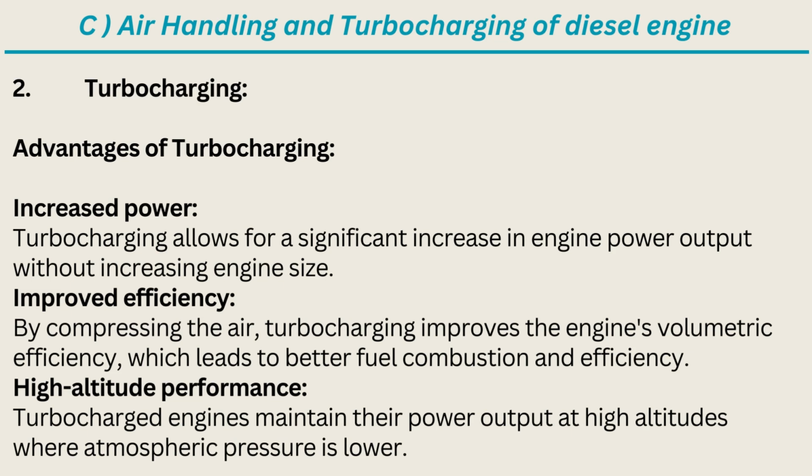Increased power. Turbocharging allows for a significant increase in engine power output without increasing engine size. Improved efficiency. By compressing the air, turbocharging improves the engine's volumetric efficiency, which leads to better fuel combustion and efficiency. High-altitude performance. Turbocharged engines maintain their power output at high altitudes where atmospheric pressure is lower.